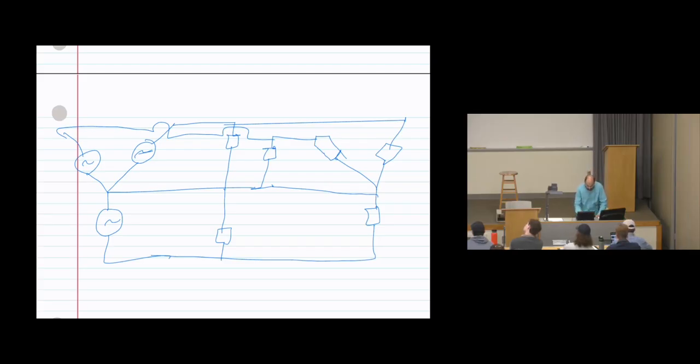How can we look at the circuits? Basically, nothing in delta, everything in Y. What should I do? We need to find the per phase equivalent circuit. To find the per phase, let's take phase A. Let's assume this is phase A, for instance. Then we can see these two impedances. I'm going to assume these as Z1, Z2 are in parallel.